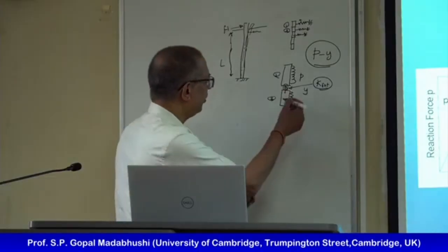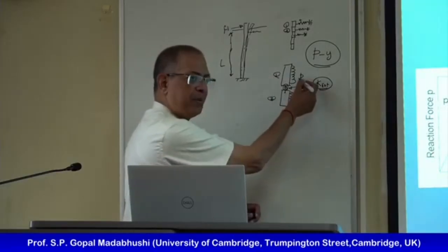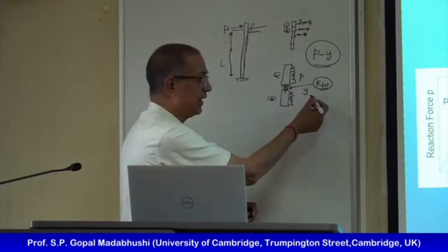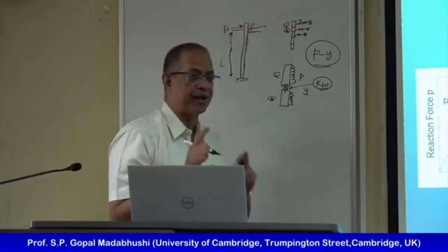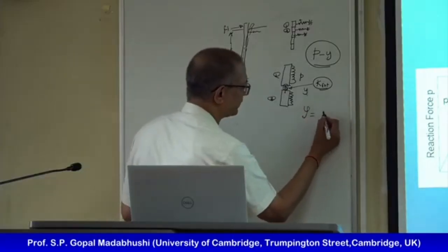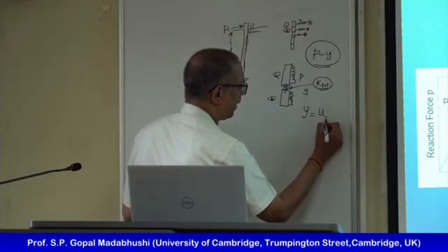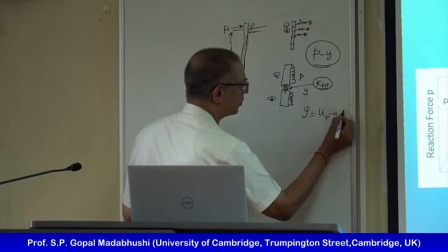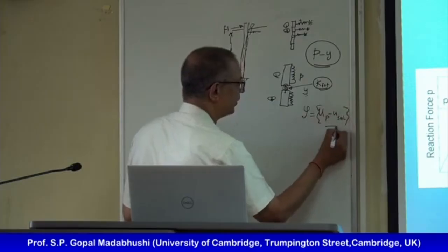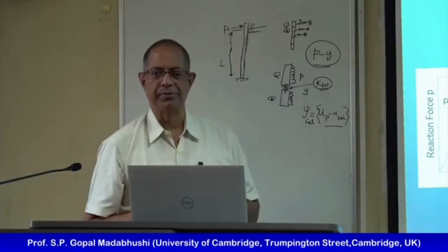Now, as I go deeper and deeper, my pressure goes up, but my deflection, the y, which is the relative displacement, I'll write it down clearly. Y is u pile minus u soil. So we should really call that a relative displacement.